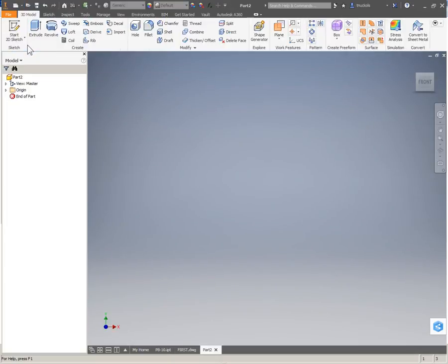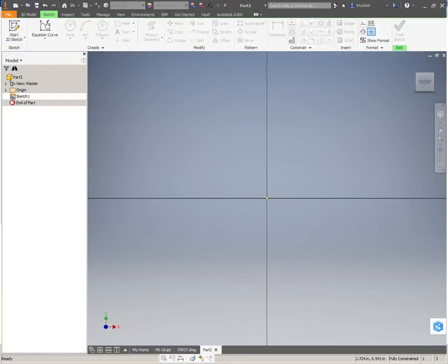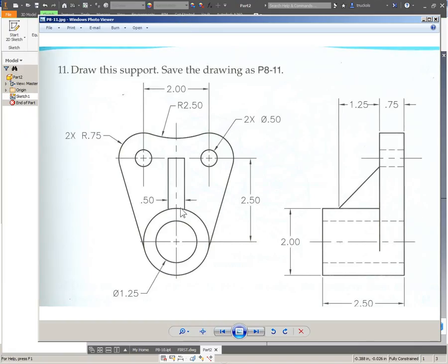The last part we created was already an English Standard IN IPT part, so this will also be the same. We're going to create a new sketch, and we're going to start on the front view just like before, which is this XY plane. Alright, very smart to always start your part so that something is created on the origin 0, 0, 0. So since this has a circle that sort of is the main thing in this part, I'm going to create this circle right there.